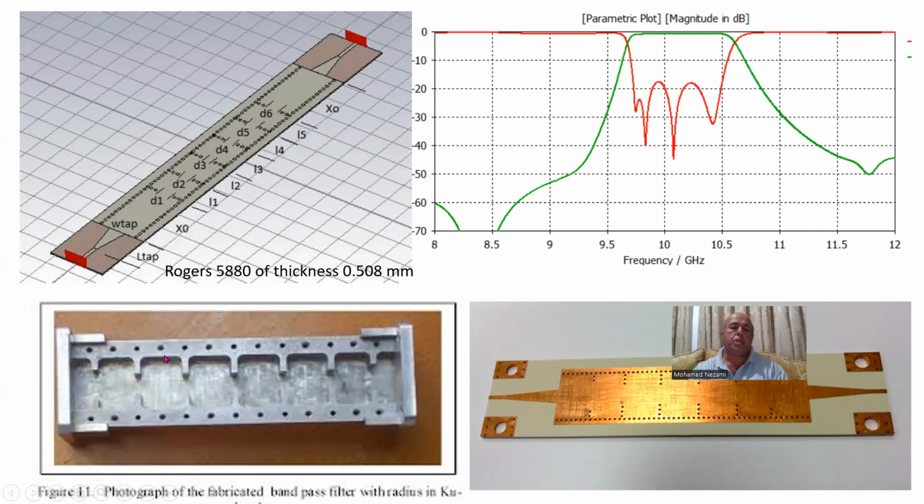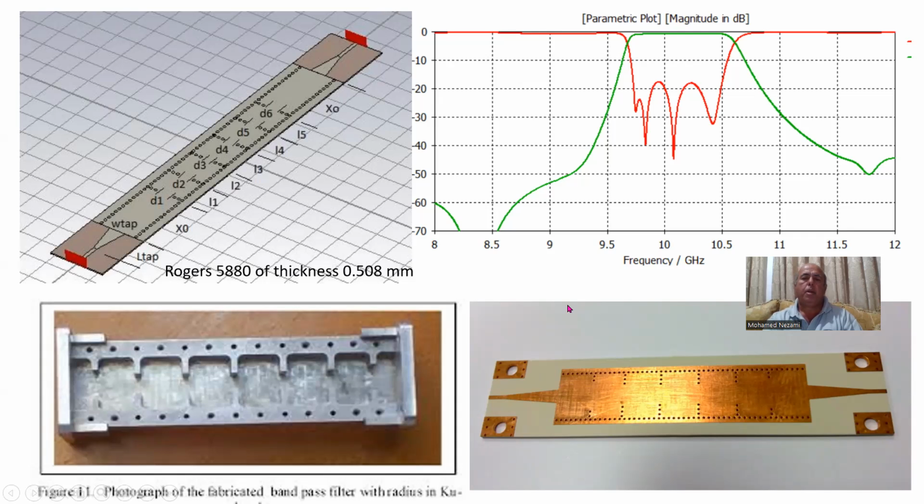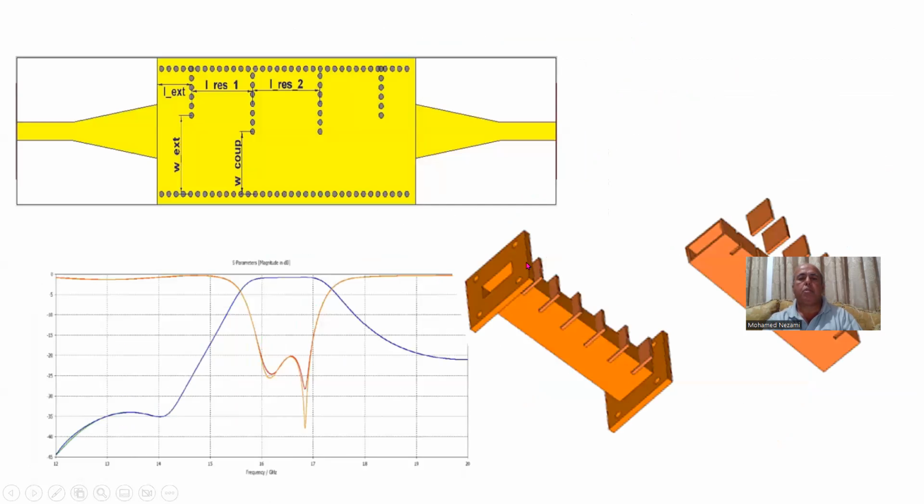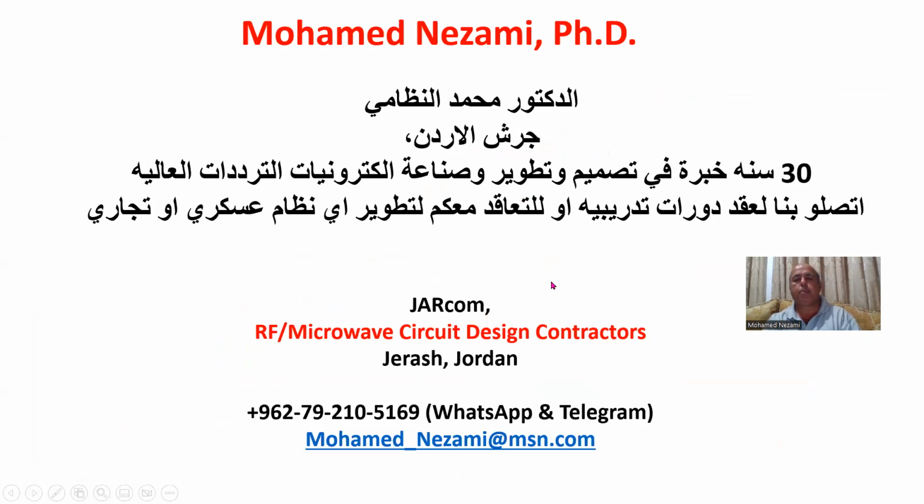And this filter very much acts just like a waveguide filter, using this structure where you have a bunch of irises in the middle. And this is how it looks when you fab it, okay? Now, there are two other types of filters. One of them is the post filter that is like this, similar to the waveguide, exactly parallel to it. And then this one here, which is basically building these sideways stubs or metal pieces on the inside.